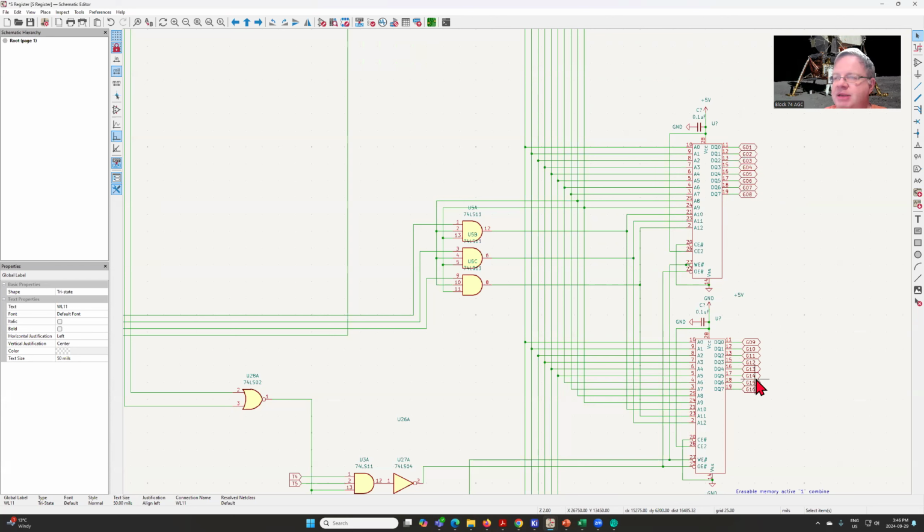Because I'm going to be implementing the parity check and the parity logic on my G board, I am going to send my G15, which is the parity line, over to the G register board. Now, the G register itself won't really see this, because when you write into the G register, the contents of G16 is written into both G16 and G15.